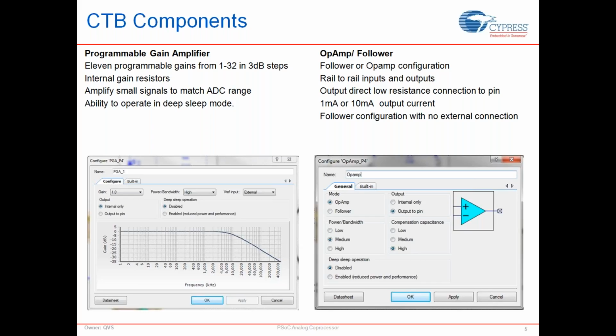You can have a setting for the power, which can go from high, low, or medium, depending on what power mode you set up for the op-amp. You have different power consumptions. So depending on your power requirement for the system, you can determine what kind of power setting you need. But based on the power setting you set up, the op-amp's gain bandwidth is also going to change. So that correlation or trade-off is something you need to be aware of when you're designing your system.